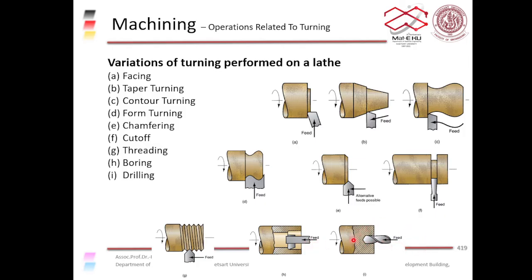Initially, they use a process similar to drilling, but for a long gun, the drill bit has to be long as well, and that is not very suitable. When you keep drilling a deep hole with a long drill bit, the drill bit gets hot and warps. So the hole inside is not a straight hole.